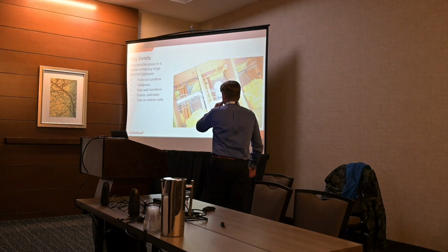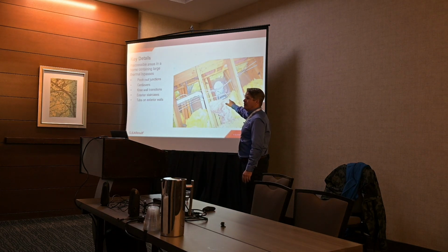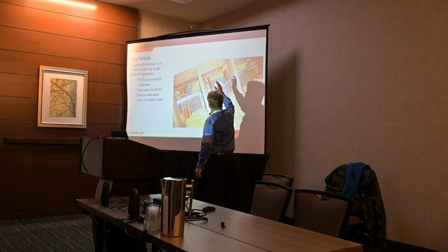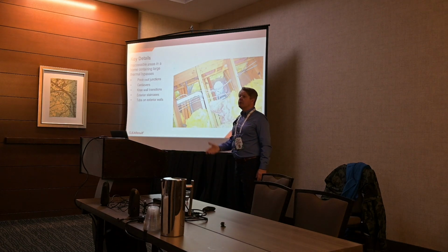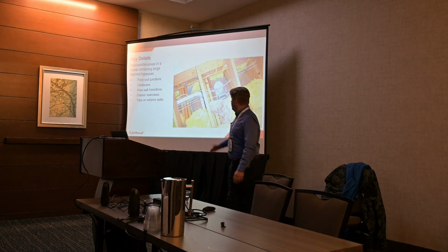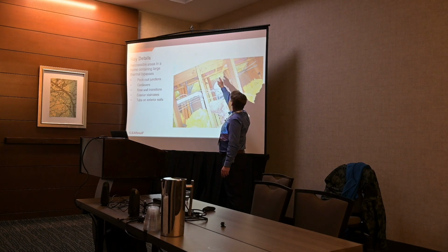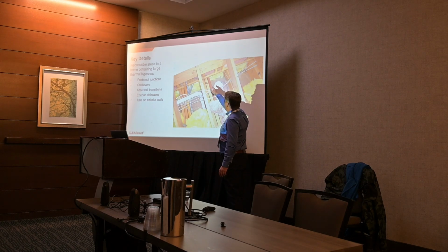Okay, so remember that porch roof we looked at before, and I said this could be a problem? This is that porch roof. It is a problem, okay? When we pulled the sheathing off and looked inside there, that's the bottom of the wall right there. It never got sheathed, which makes it susceptible to wind washing, right? So when the ventilation air comes up into this porch area, it's going to go over there, and it's going to wind wash that.